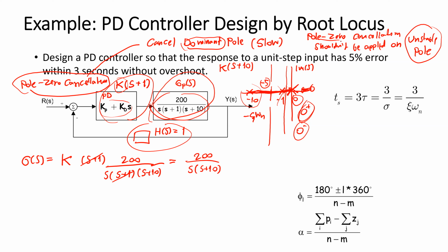When it's positive, also, if you have the pole somewhere here, you cannot directly put the zero on it to have the pole-zero cancellation, because in the analytical way, you know the exact, you can predict the location of the pole, but in practice, it's impossible to find the exact position of the pole.